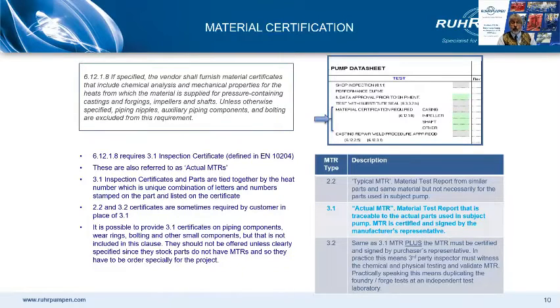Commercial foundries will pour the castings as and when they have a batch of material ready to pour. They'll not generally be able to give 5 days notice and tie it down to a particular day or time. Now, some high-end foundries, for which you can read expensive foundries, have third-party resident or regularly available inspectors and will be able to accommodate this, but at a price.